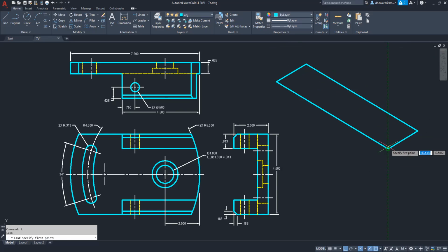Now I'm going to go down. And in order to go down, I need to change planes. It doesn't matter which one. I'm going to hit the F5 key and pull downward the overall, you know what, not the overall, because I need to get to the midpoint anyway. So I'm going to pull down 2.25, 2.25, and then I'm going to keep going another 2.25.